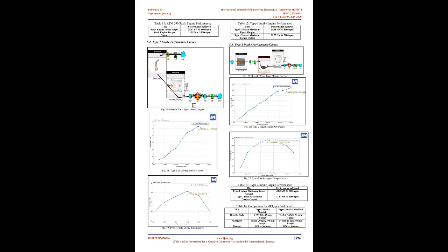Table 10, comparison between plenum simulation outputs. Volume: 3000 cubic centimeters and 3150 cubic centimeters. Volumetric efficiency range: 85.2% and 91.43%. Outlet pressure: 77,043 Pa and 93,774 Pa. Fig 12, plenum result volumetric efficiency comparison. Fig 13, plenum result pressure comparison.